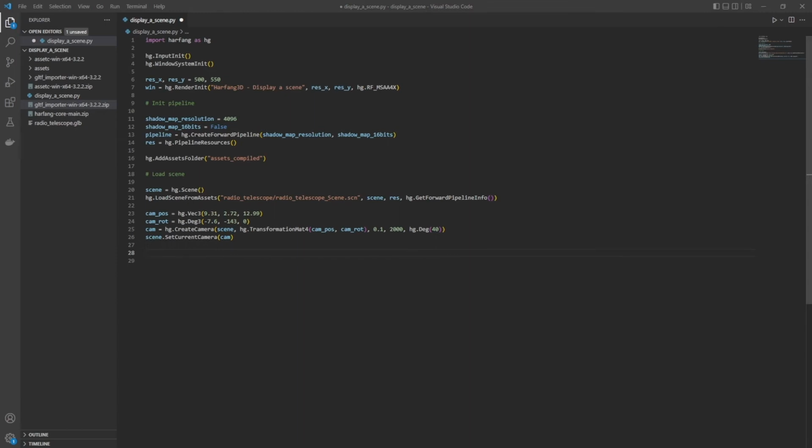Then we will define different display parameters of the scene. Set scene environment. First, the background color, which is accessible in the canvas. Scene.canvas.color equal hg.ColorI. We will define the color thanks to integers from 0 to 255, 88 in red, 151 in green level, 206 in blue level. Then we will define the color of the fog.